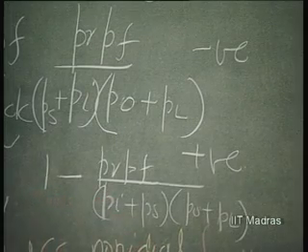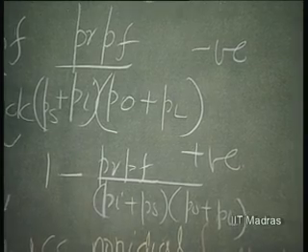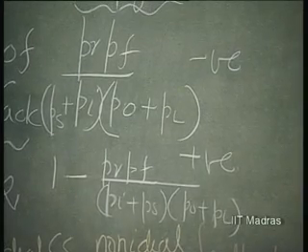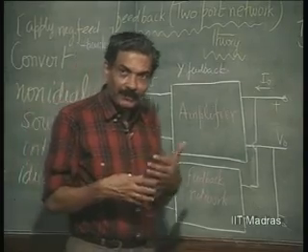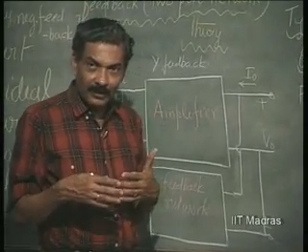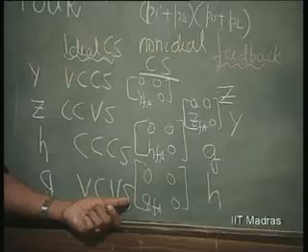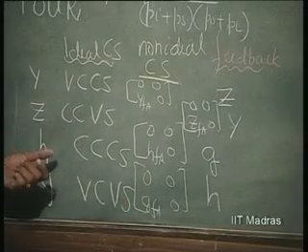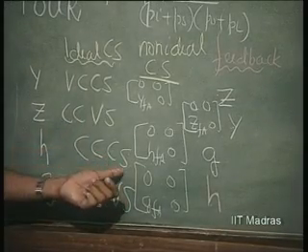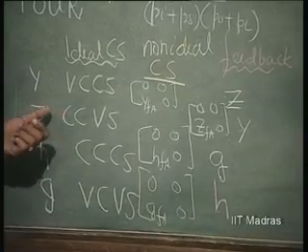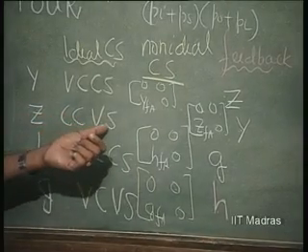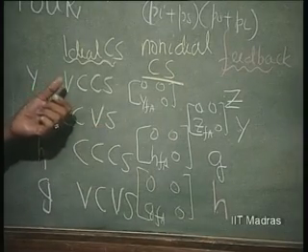So this is the consistent way we can define all types of feedback and also know what we are aiming for. Are we aiming for design of an ideal voltage controlled voltage source? Are we aiming for an ideal current controlled current source? Are we aiming for an ideal current controlled voltage source, or an ideal voltage controlled current source?